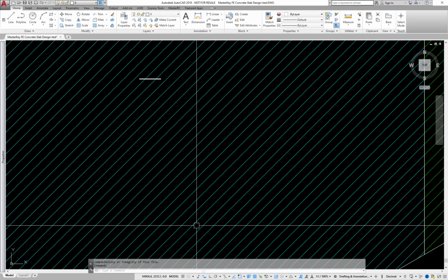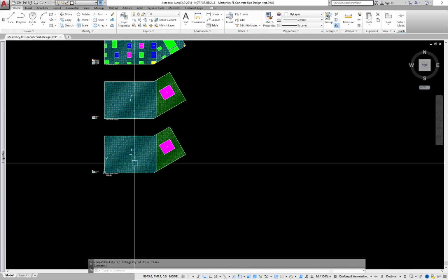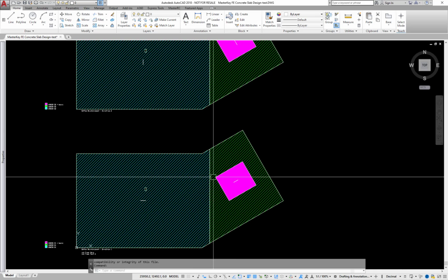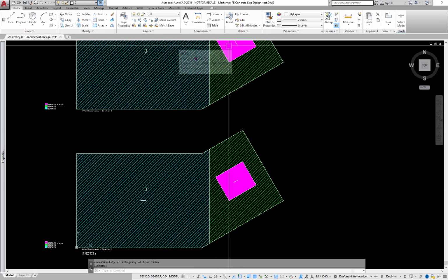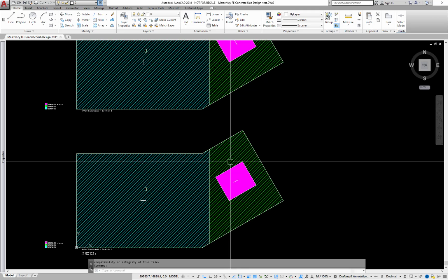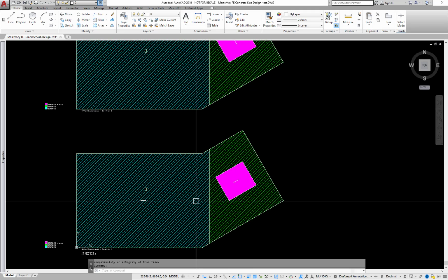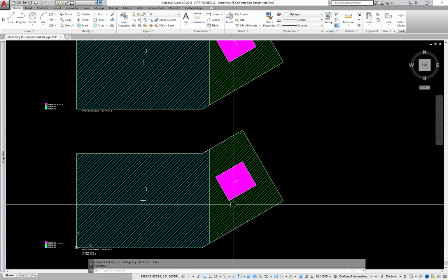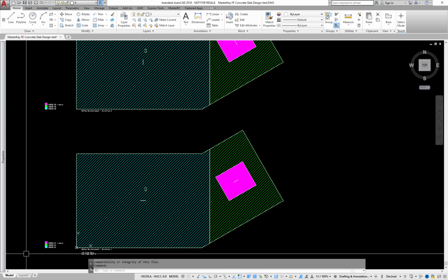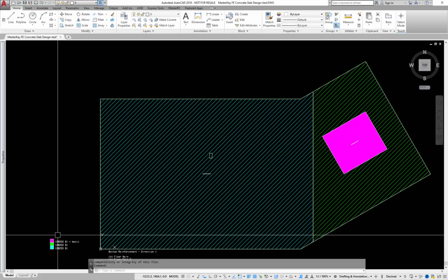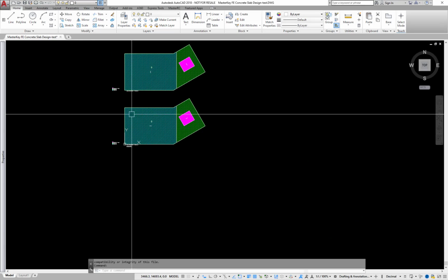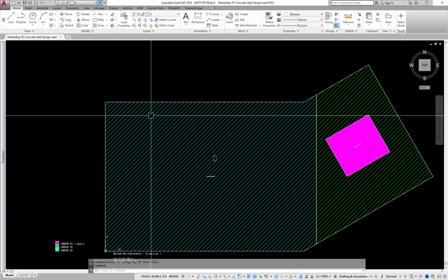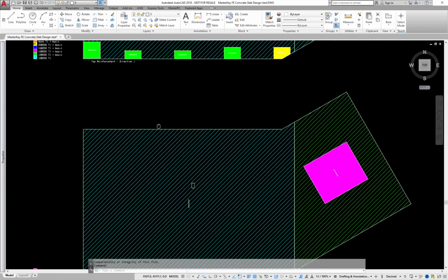And here we go. For the bottom steel, we have this big area we need to enhance for the transfer slab, the big beam action in the slab in here. We've got heavier reinforcement in this zone than in this, so we went for 12s as the default rather than 10s, and that's in the X direction, and the Y direction is the same.